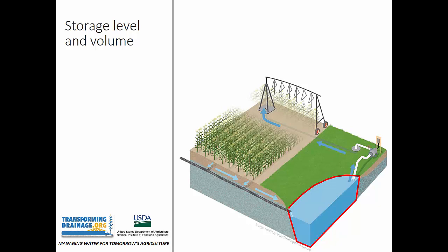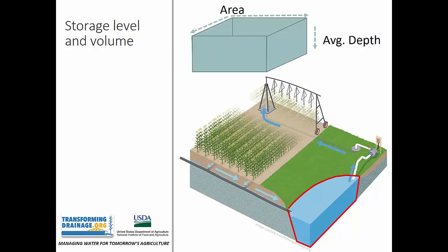So now looking at the water storage component of the system, we again needed to identify physical boundary parameters. So first, in defining a maximum potential storage volume, we wanted to simplify pond geometry, just because this can vary widely based on what type of pond or reservoir it is. And so we characterize water storage by relative or average depth rather than a maximum depth.